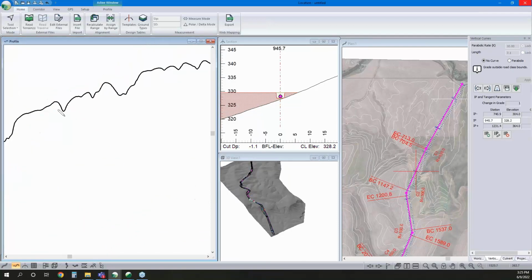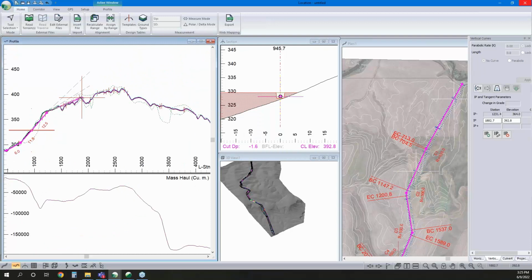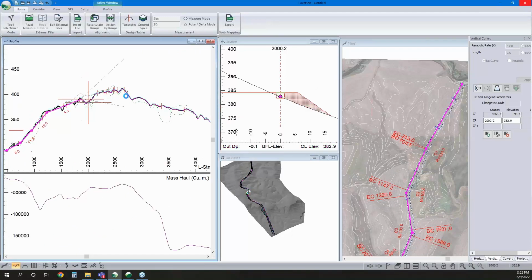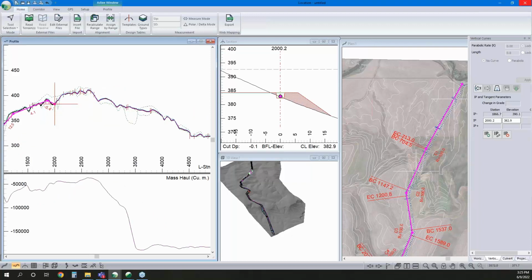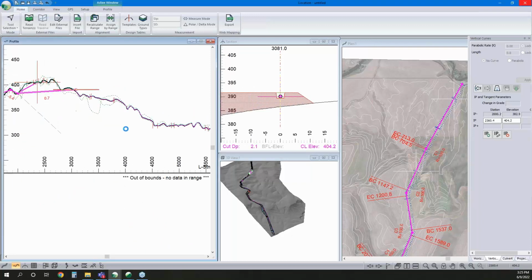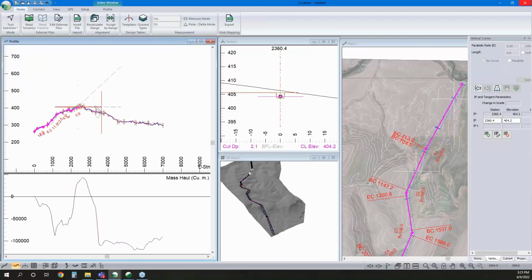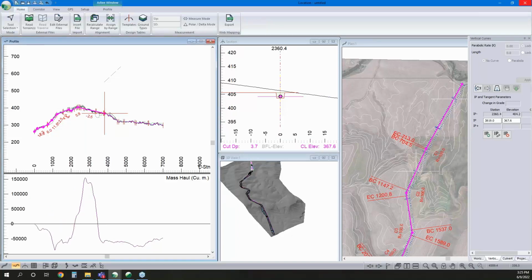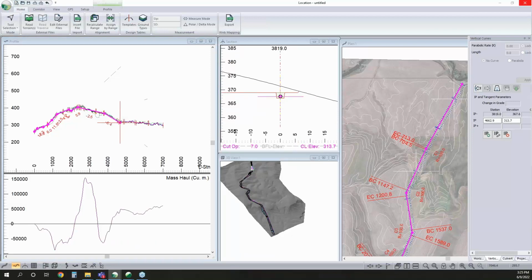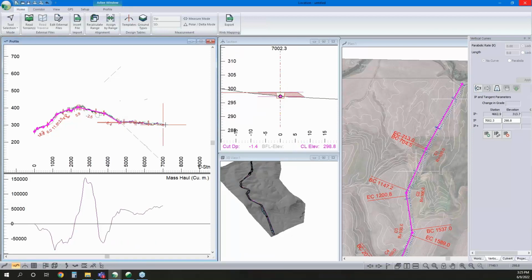And I'd want to maybe wiggle around to follow the ground as best I can to reduce those earthworks. And we can see as we make our adjustments, we have our mass haul diagram down here, which is tracking our surplus cuts and fills. And again, I'm just going to rough this in really coarsely just for concept for now before I jump into the optimizer.